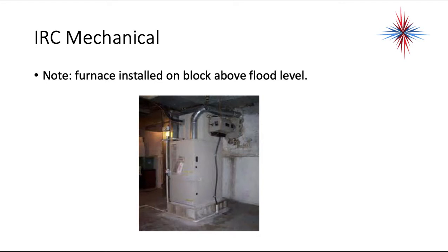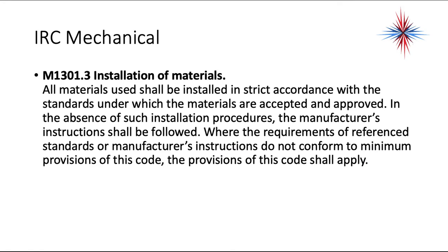You also have to make sure that in areas where it's possible for flood hazards to occur, for example in a basement, the equipment should be installed above flood level. And notice the furnace in the pictures on blocks. Things need to be protected from floods.